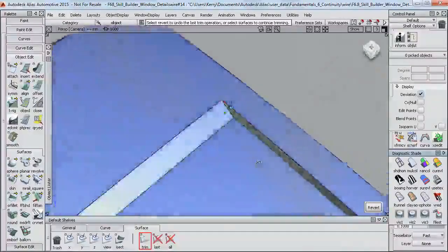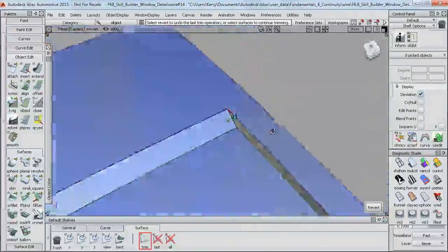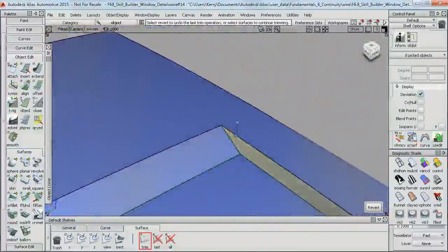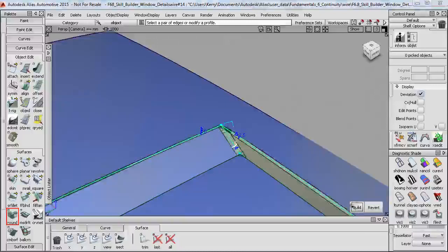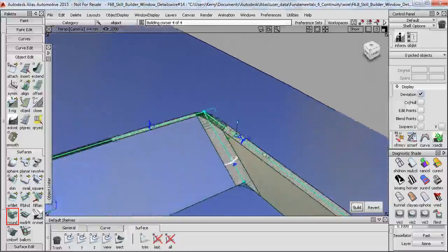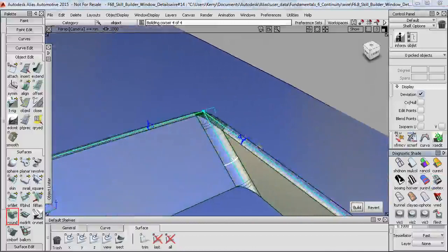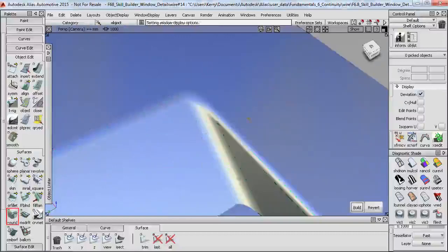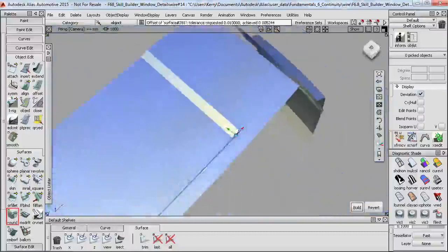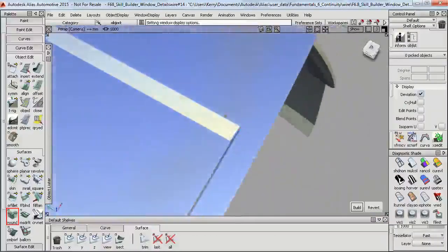Now if it looks too sharp, then I might want to soften it off with a fillet. So I just want to show you how the round tool deals with corners. So I'll choose round and then put values on each of these edges. And I'll change some of the radii. So when I have edges coming together, then Round will build the corner blend. So it's limited to tangent only, but being able to build that corner blend is one of the advantages over Surface Fillet. So you can see that it's just given a more realistic finish to that edge feature.